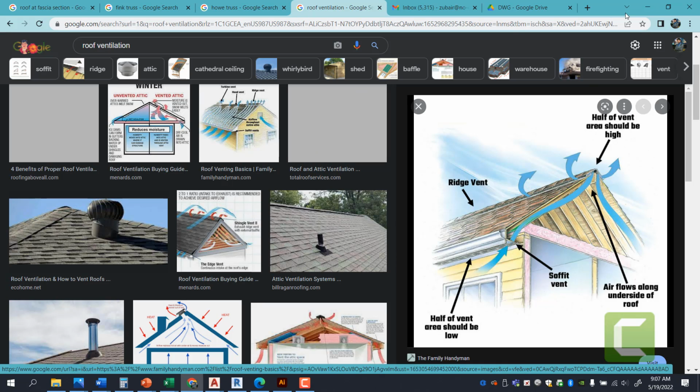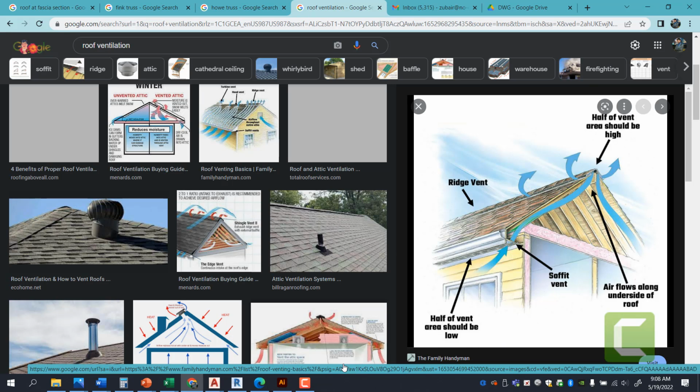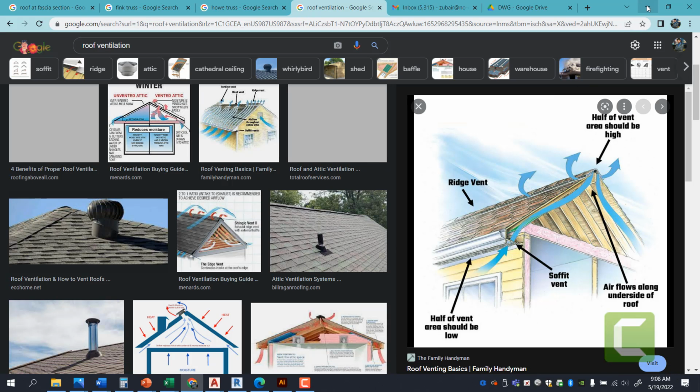your attic. Now, contrary to popular belief, your attic should be around 120, 110 degrees, maybe around 10 to 20 degrees warmer than the outside air. It should not be exceeding 30, 40 degrees excess of outside air, because you really have an issue with your framing starting to wane. And that means the wood or the framing in your roof has started to leak out the oils that the wood has inside of it. Over time, the wood will become harder, but it will become more brittle because it will lose that flexibility.